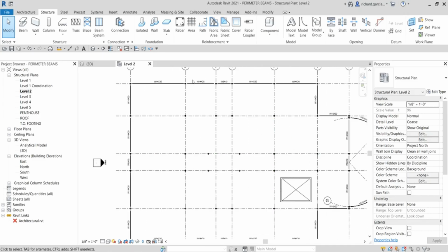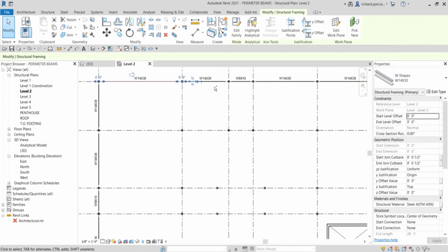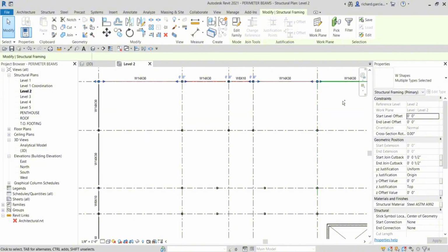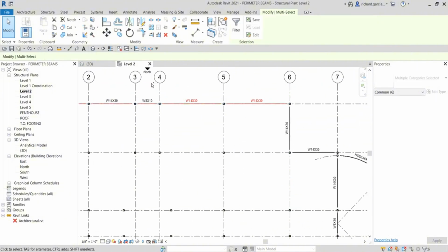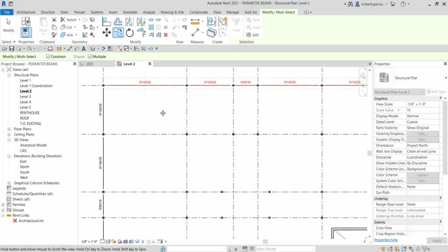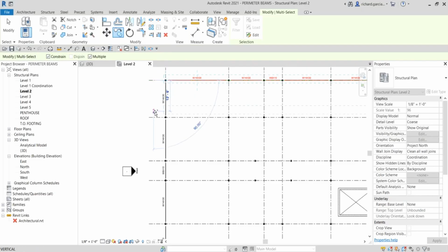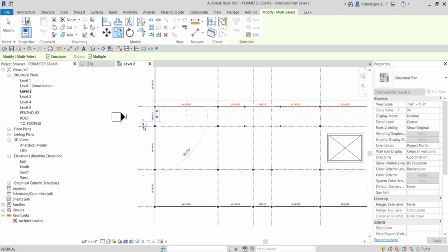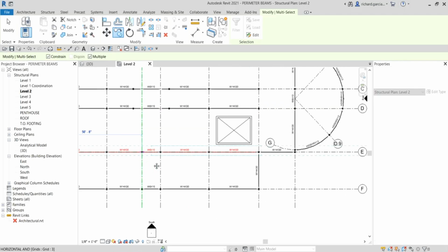You can actually use copy, so let's try to use copy. Let's select this, click, hold control, then click these beams, this framing, including the tags. So hold control, select the tags together with the frame. All right. After selecting these elements, let's copy it. Multiple constraint. Okay, so I'm now going to click here. Click. So we're going to fix the beam somewhere here. Okay, so I'm just going to copy this. Okay, click. There you go.